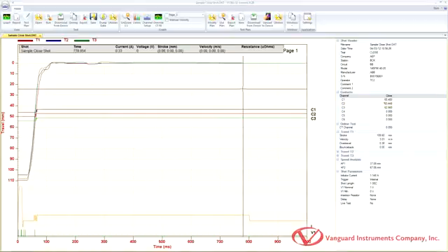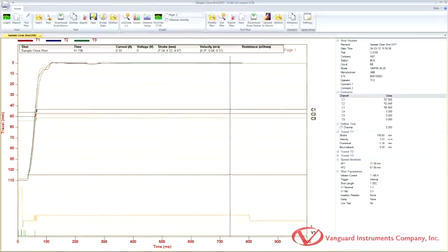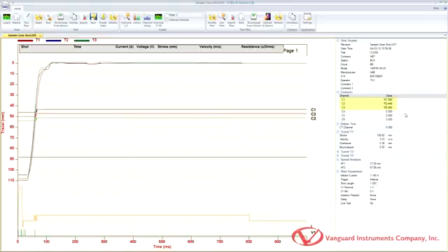You can also manually enter override values for multiple contacts. For this example, we will also override values for contacts 1 and 3. First, press the F8 key on your keyboard or click on the Override CT icon in the Graph command group. Now, click on the Enable checkbox next to the Close input field. The value from the cursor will be inserted. Replace this value by typing your preferred value. Now, select Contact 3 from the drop-down menu and follow the same steps. Click on the OK button when done. Note that the tabulated results now display all the overridden values.